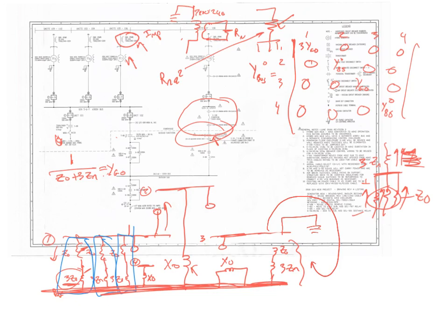Ethan, did you have a question? I did, but the guy asked. Okay. Are those values supposed to be negative, that diagonal from the Y bus, or are they positive this time? It's the other ones that are the opposite of. You only subtract the negatives here. The diagonals are just added up. They tend to be negative because the transformers and generators look like resistors and inductors. So when you invert an inductor, it becomes a negative J term. So you only have negative J's because you've inverted it. Notice these are all Y values, right? They're not Z's. Okay, so that's only true with Z's that you have that negative, if they're inductors. If they're inductors, yep.